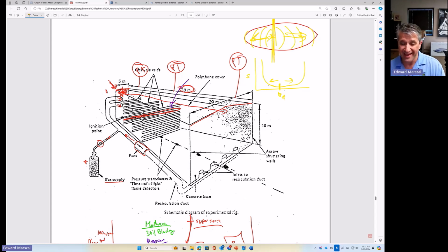So it's definitely a lower consequence scenario. The biggest consequence you're going to get is when you ignite at the edge, because you maximize the distance of flame travel. When you maximize the distance of flame travel, you maximize the degree of overpressure, which maximizes the amount of damage that occurs.